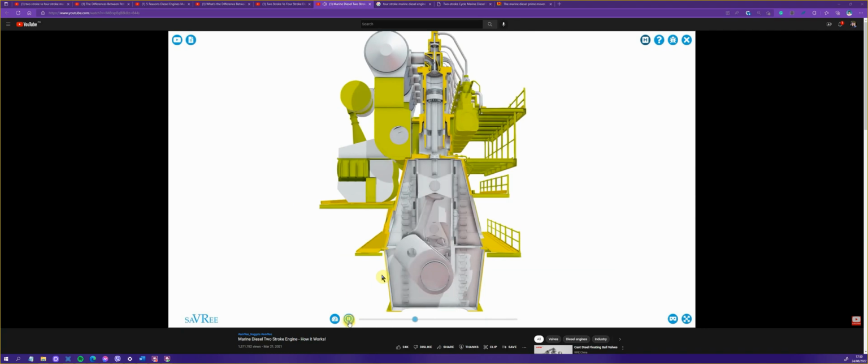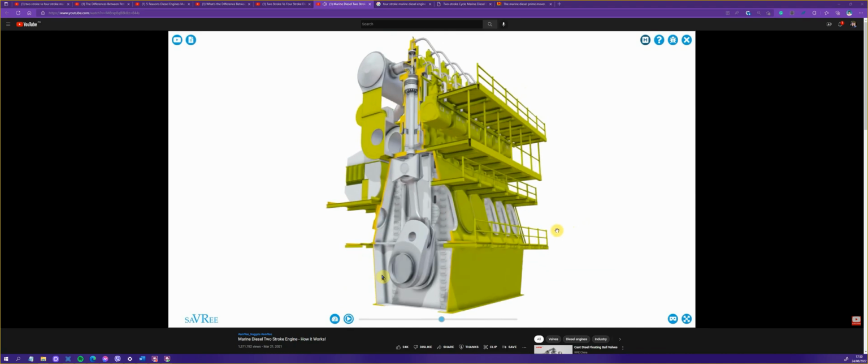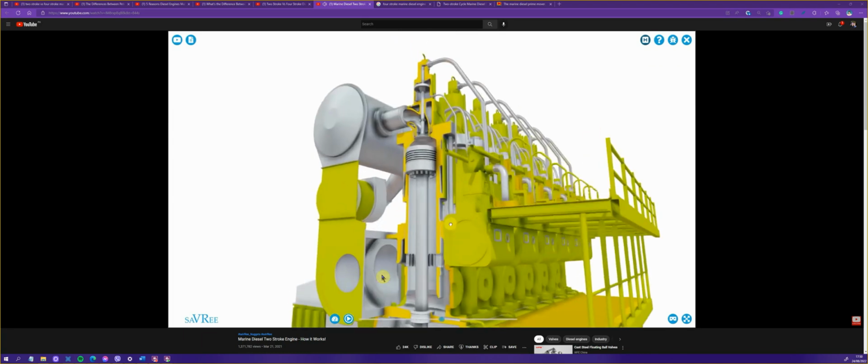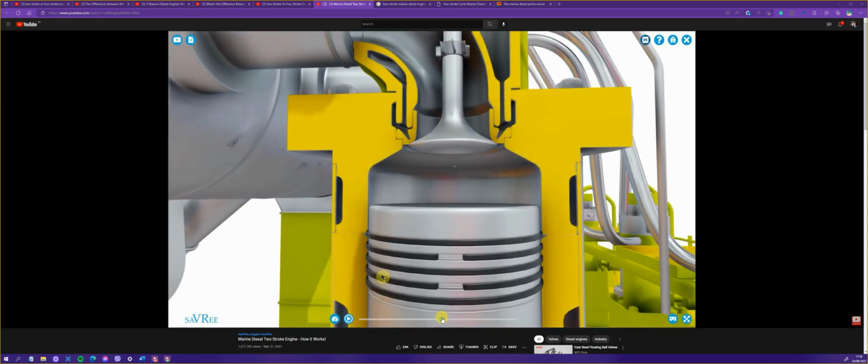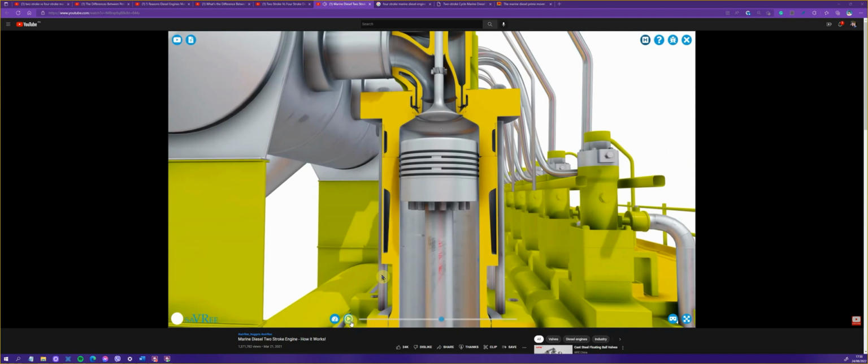I mentioned that we can use a turning gear to turn the engine very slowly. The reason we do this is because when we start the engine, we use compressed air. We're going to feed compressed air into the combustion space in order to drive the piston downwards towards the crankshaft. So let's imagine for a moment we feed compressed air into the engine.